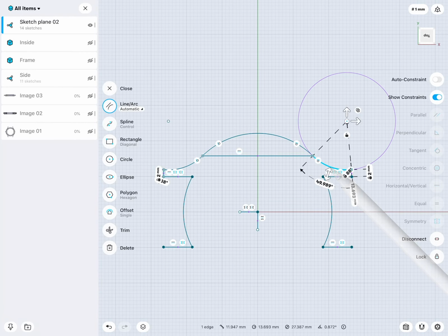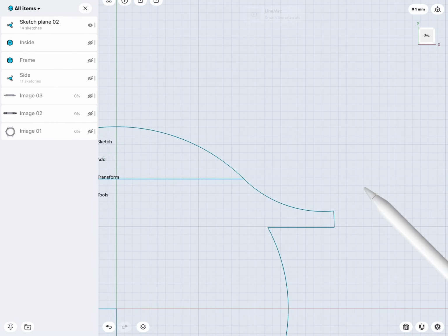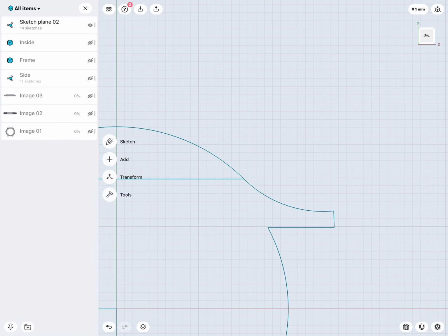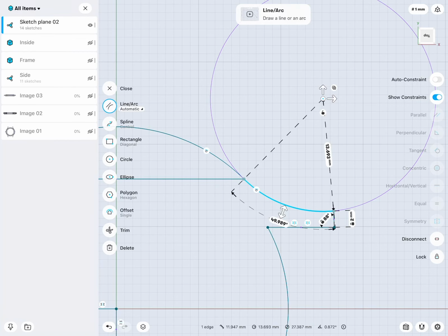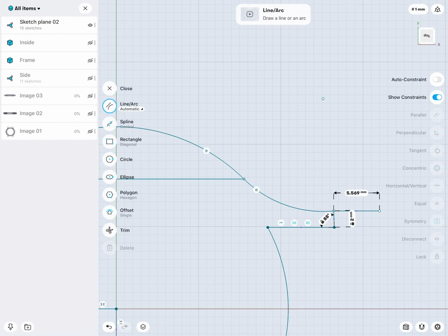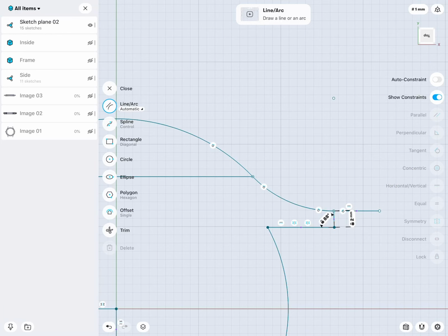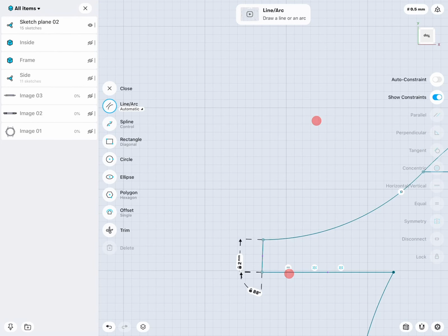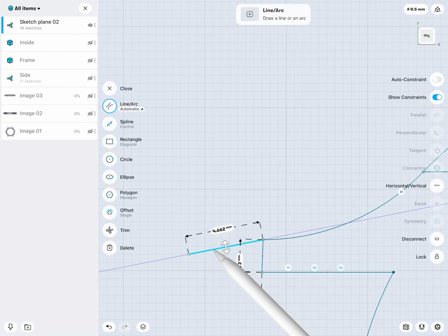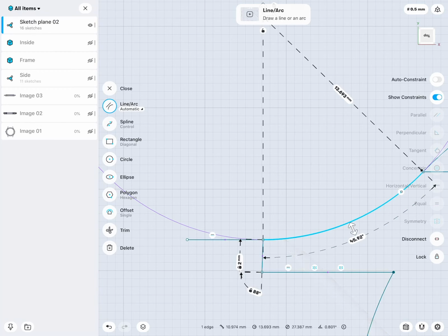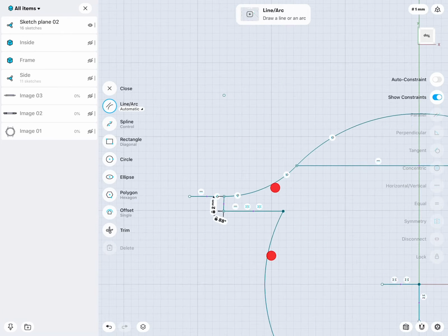And these arcs at these ends here, right there at the slot, they go up way too much. That's not what I like. So I will do the following. I will draw here a line, make the line horizontal, and then the line and this arc I make tangent. And you see how this actually moved this arc up. So I will do the same. Draw a line to there. This line has to be horizontal because this line is at an angle, and then line and arc tangent.